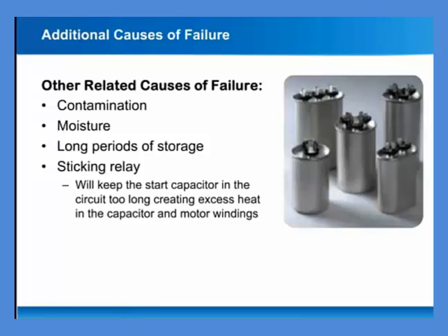When a capacitor fails, in addition to checking the capacitor, the technician needs to be certain that the motor is operating properly as well. For example, a sticking relay will keep the start capacitor in the circuit too long, creating excess heat in the capacitor and the motor windings.